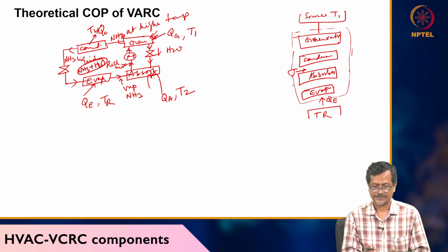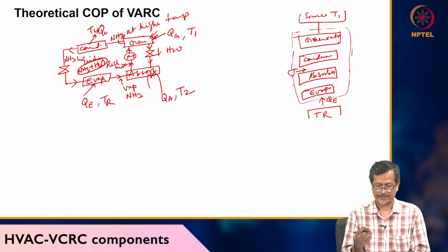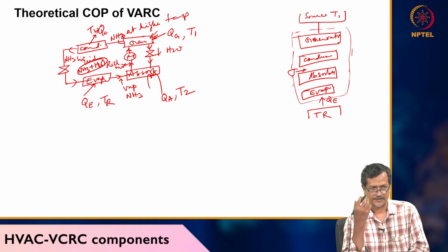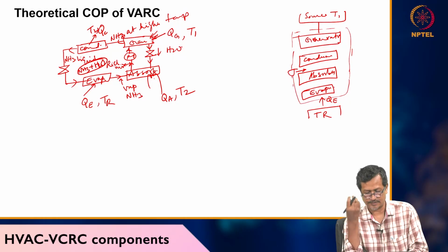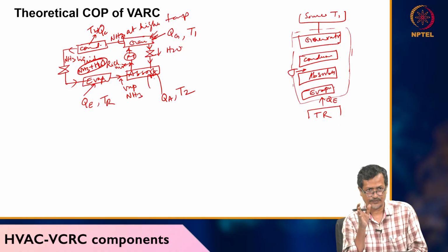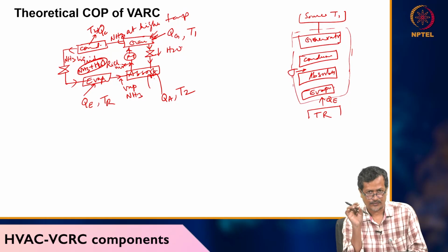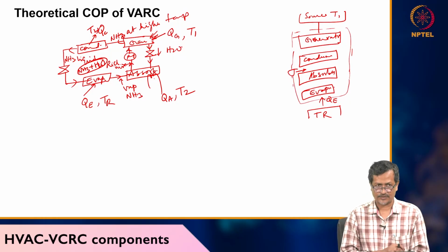The good thing about this system is that it takes or releases heat in the surroundings, especially in solar air conditioning systems. Heat is required in the generator section, where you are separating your ammonia and water, or water and lithium bromide. That heat may come from waste heat sources; anywhere there is any waste heat, you can use it.